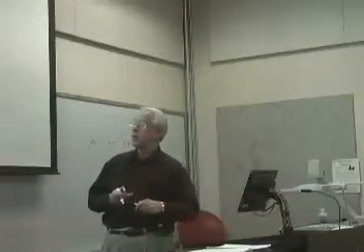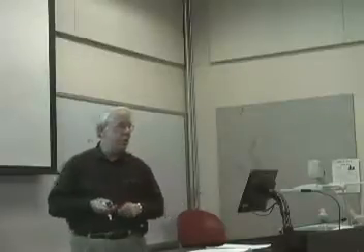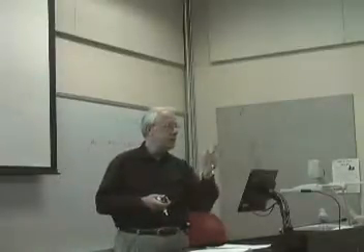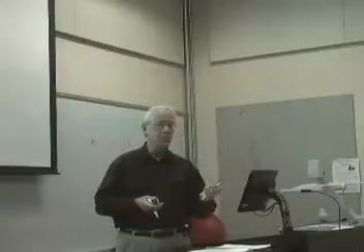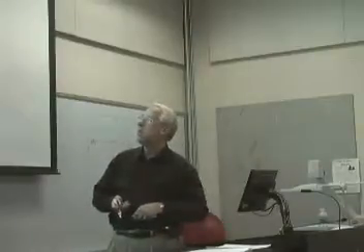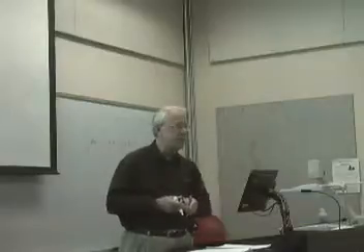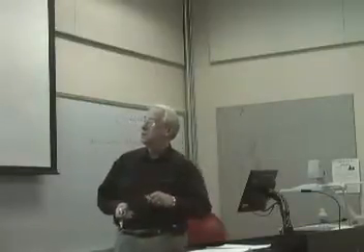The other element, quadrilateral. Quadrilateral, four-sided. It doesn't have to be rectangular. It doesn't have to be orthogonal. So it can be skewed, whatever it is. I will transform that into a unit square in computational space because I will be doing an integration by parts and Gauss quadrature where the limits go -1 to 1. So I can take advantage of that and transform x and y into coordinates psi and eta. And so those are going to be orthogonal in computational space. That's fine. It's very simple to set this up.